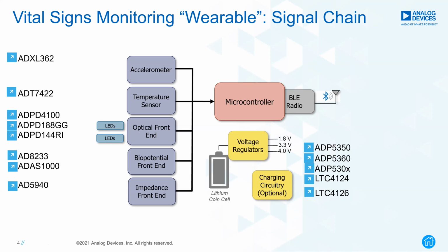Whenever you see a movement on the wearable, this accelerometer detects that and again powers up the remaining circuitry. This is one of the use cases. In that mode, this device would consume around 270 nanoamperes. This is the low power performance, along with the noise performance of these accelerometers.